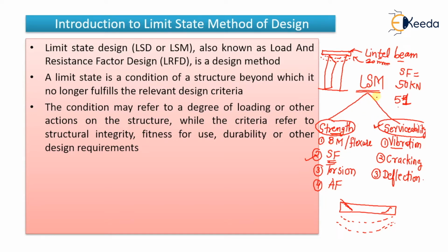So as per the LSM, what is the concern? It should fulfill the requirement of the strength, and it should also fulfill the requirement of serviceability. Okay, means it should be fit for the use. Now I have given you the example of this lintel beam. It is not fit for the use, na? So it should be fit for the use. It should give you the structural integrity. Structural integrity will be related to the strength. It should have durability and other desired requirements. So if my structure is fulfilling all the requirements, then and then I will be designing this by LSM.